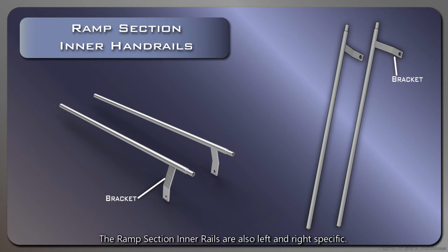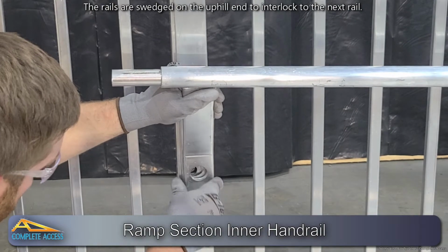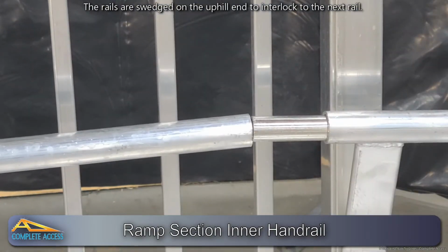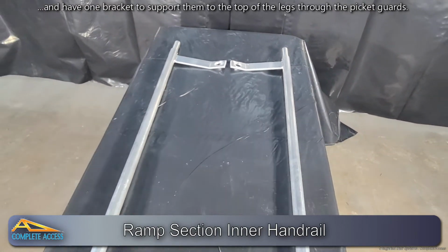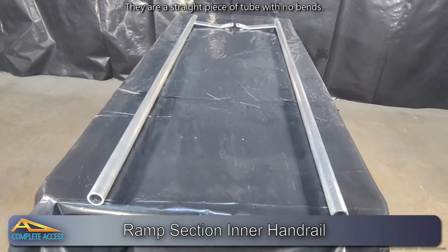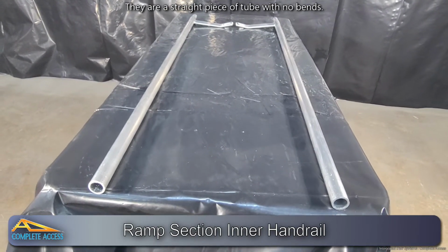Ramp section inner handrails are also left and right specific. The rails are swedged on the uphill end to interlock to the next rail, and have 1 bracket to support them to the tops of the legs through the picket guards. They are made of a straight piece of tube with no bends.